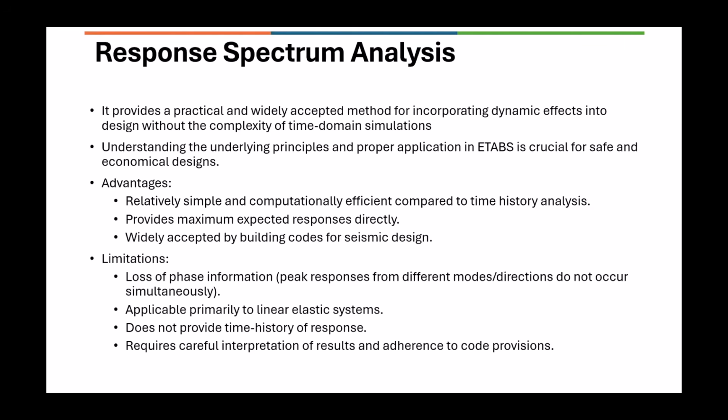In other words, it is a shortcut from an actual time history analysis that you would require to understand the dynamic properties of the structure and its responses. But for a design office requirement, we are interested in the peak responses for the design of the members.